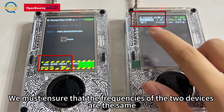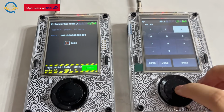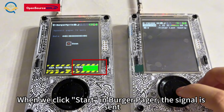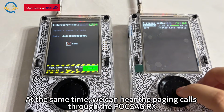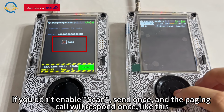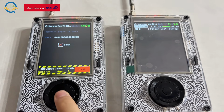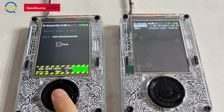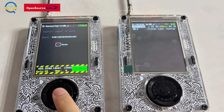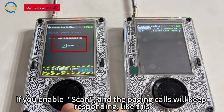We must ensure that the frequencies of the two devices are the same. When we click Start in Burger Pager, the signal is sent. At the same time, we can hear the paging calls through the POCSAG RX. If you don't enable scan, send once, and the paging call will respond once, like this. If you enable scan, the paging calls will keep responding, like this.